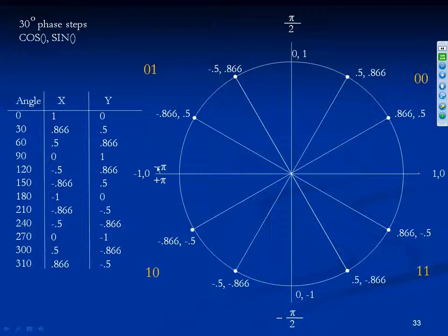As you count from 0 to pi, you go from a 32-bit value of 0 up to a 32-bit value of 0, 1, 1, 1, 1, 1, 1, 1, and so on. Then starting right here, you have the most significant bit of that 32 bits set to 1, and the rest of the bits are 0, and then it counts on up all the way to all 1s for the 32-bit value. So you'll notice that 32 bits of 0 all the way up to 32 bits of 1s is the equivalent of 2 pi.